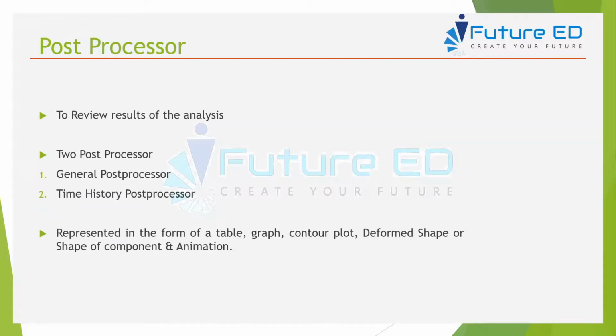And the next comes the post-processor. The post-processor is completely about knowing the results which have been defined for the solid body, the cylinder. The results you will be seeing in the post-processor. The post-processor results are in the form of a table, graph, contour plot, deformed shape, or an animated view. These are the ways the post-processor works, where the analysis can be shown through a graph or any plot.